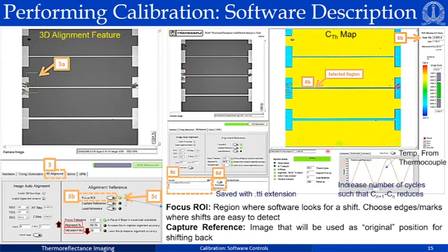If you look at the second screen, on the right hand side, you can monitor the temperature measured from the thermocouple, where the multiple number of cycles that you choose would be visible. The temperature rise from room temperature to the heater temperature and then the subsequent falling back can be monitored here. So how do you know that the measurement is going on? The status bar will continue to move. The system status will reflect heating whenever the stage is heated.